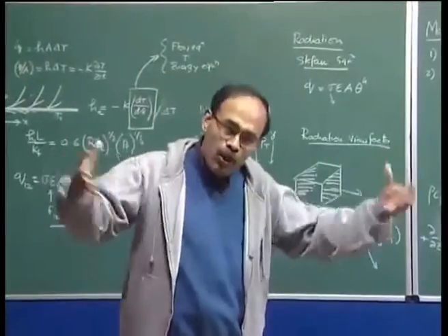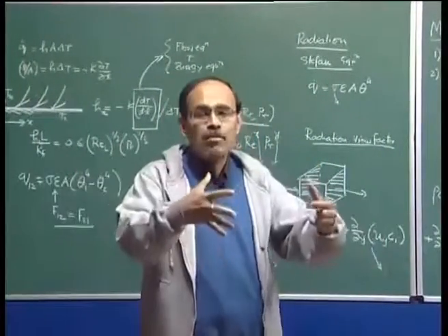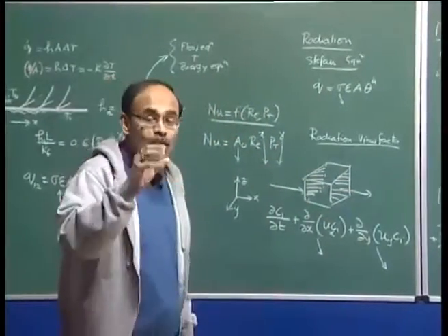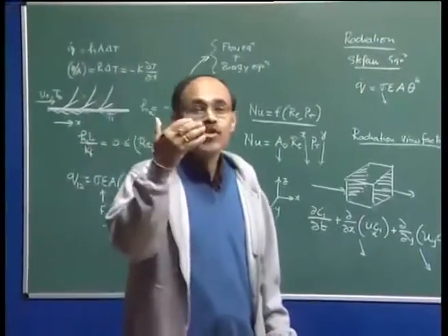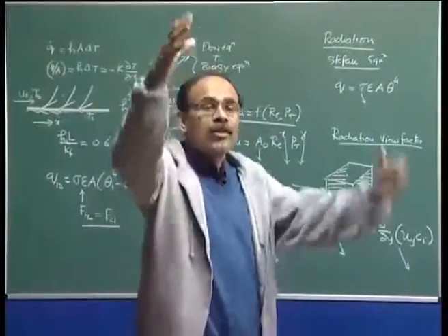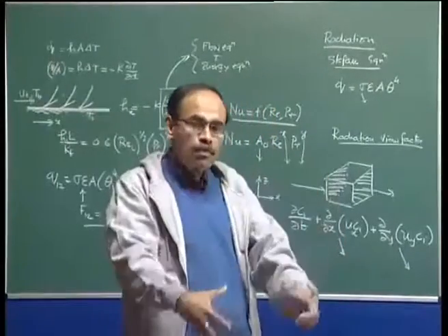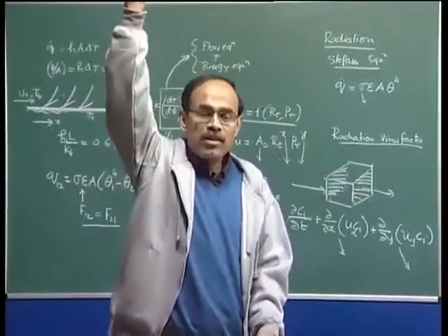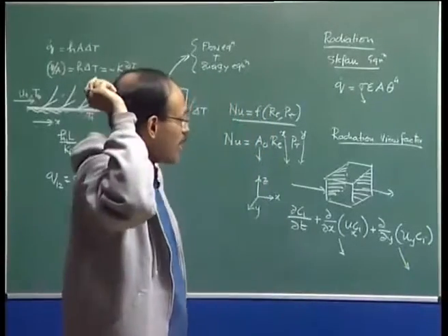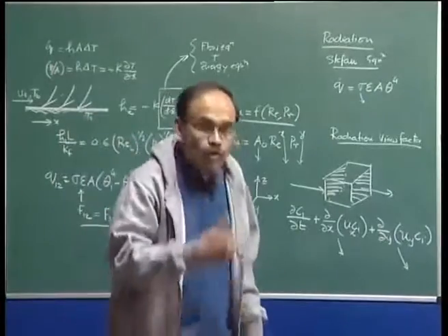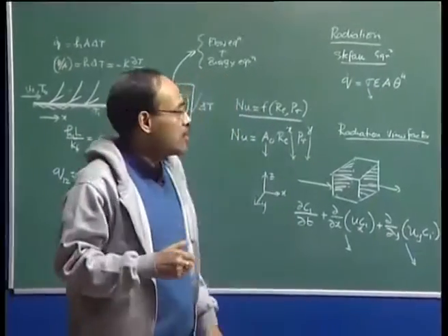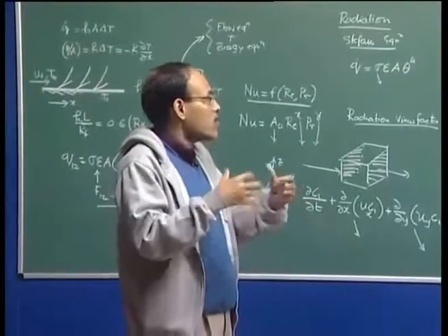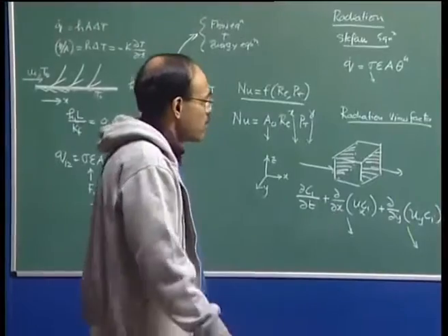Now, if you have both free convection heat transfer and free convection mass transfer, because of temperature difference as well as concentration difference, we call that convection thermosolutal convection. For example, in continuous casting, if you go towards the lower part of the bloom or the billet, where there is virtually no stirring effect felt of the material coming through the SEN, whatever weak flow you are going to see would basically be due to thermosolutal convection, because there is going to be a temperature differential in the fluid as well as a concentration difference in the system.